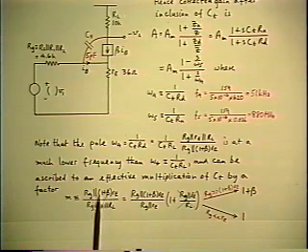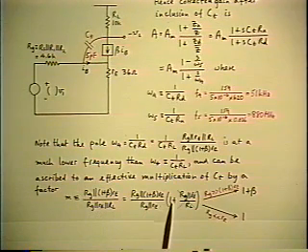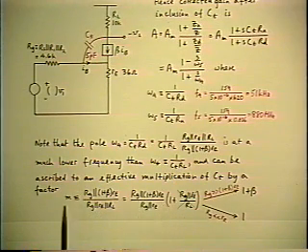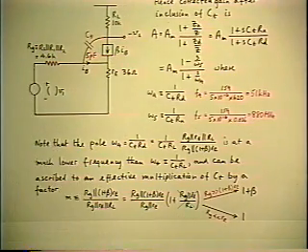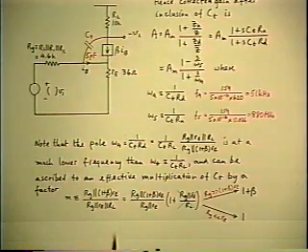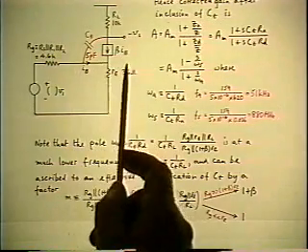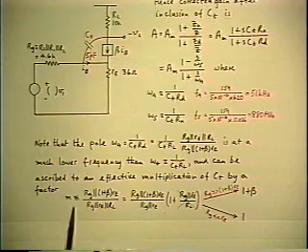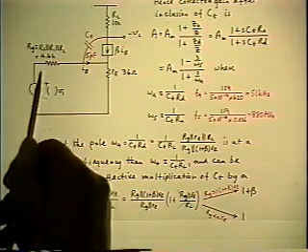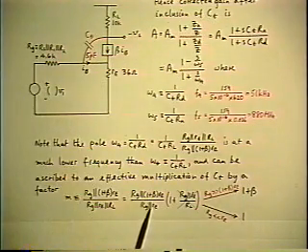And it's this ratio of parallel quantities. So I rearranged that a little bit to expose the fact that this multiplier is a function of the source resistance, which in a sense is external to the amplifier stage itself. And it's important to recognize that this multiplier does depend on the source resistance that you're driving the circuit from.